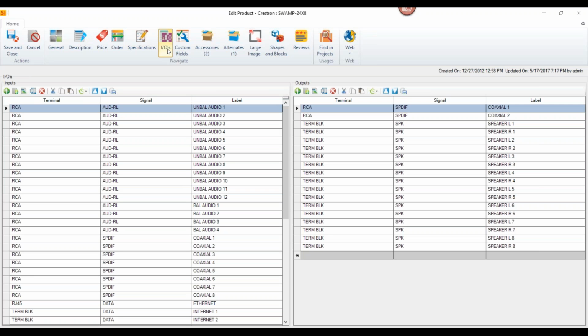As well as your IOs are here. This is for doing wiring diagrams. So you can simply drag and drop your parts out and make your cable connections. And what's really nice is this actually gives us some really good installation tools. Based off the drawing, we're going to get a wire checklist. We're going to get wire numbers auto-created, and it even creates all your wire labels for you too. So that's hours of labor right there eliminated and also automated in this process.